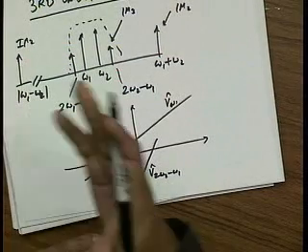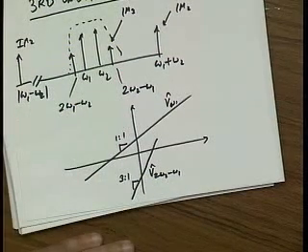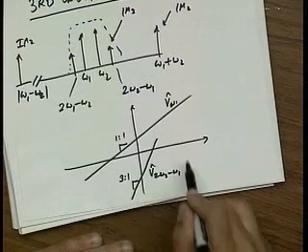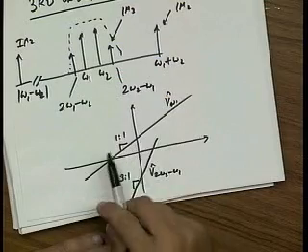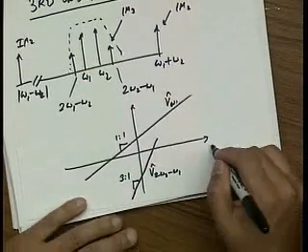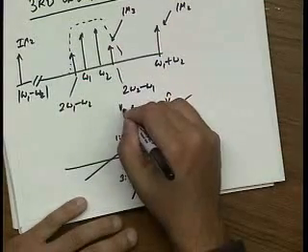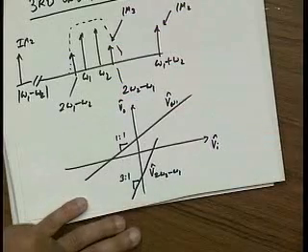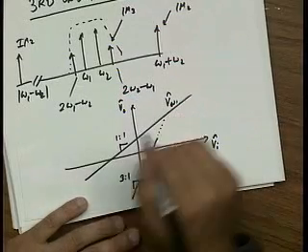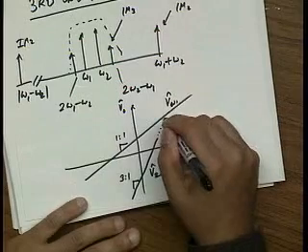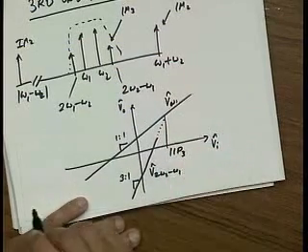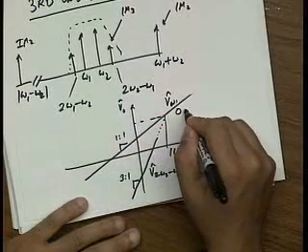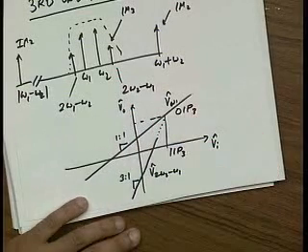That's because we know intermodulation goes like the cube of the signal. So this IM tone catches up very quickly because it's moving 3 times as fast on a log scale. And again, I can define the intercept point. And I call this my input IP3 point, and this point my output IP3 point.